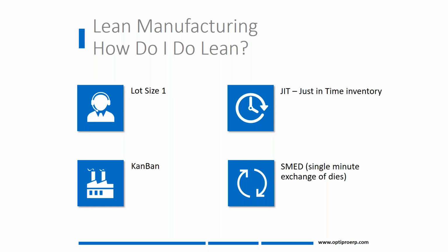So shutting down a machine so that I can do a die changeover is actually a waste operation. As much as it's something we have to do, it is a waste operation. So sitting down and figuring out how I reduce that downtime is what SMED is all about.